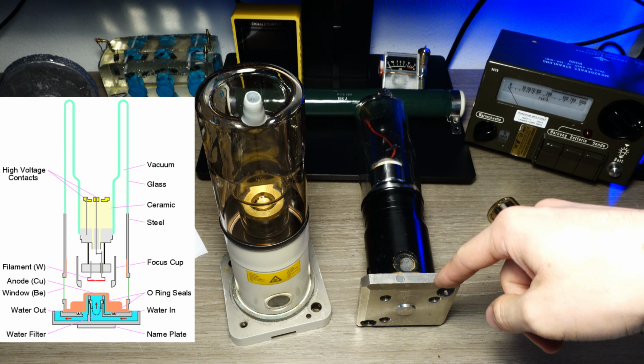The lower dimension beam, so the one with the finer focal spot, that is almost like a spot, was used, for example, in the Bragg-type XRD cameras, while the modern ones almost always use the wider beam, because you have more surface area, and due to the geometry of the modern X-ray diffraction machine, you can take advantage of all of the X-ray beam used.